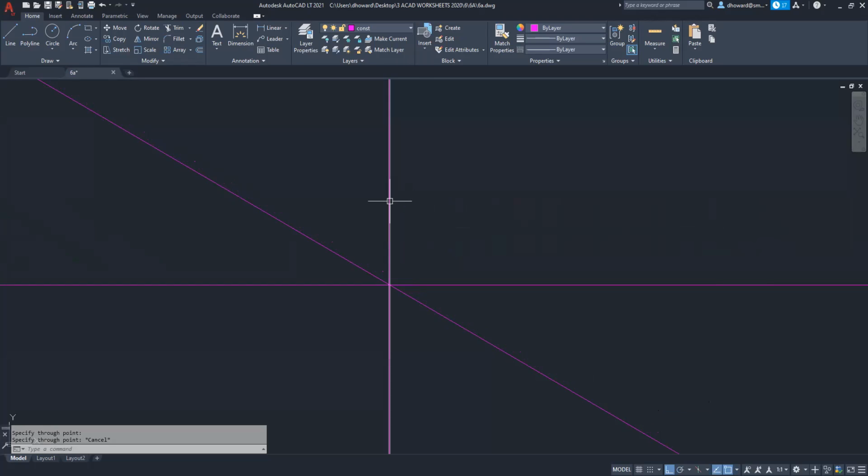And so we should be able to measure from this vertical line to that line and get a 60-degree angle. That is how it's dimensioned. So we'll see about that in a little bit. As you know, I can't check these lines because you can't throw a dimension on construction lines. Weird little glitch with AutoCAD.